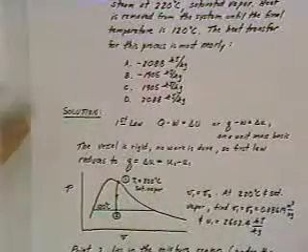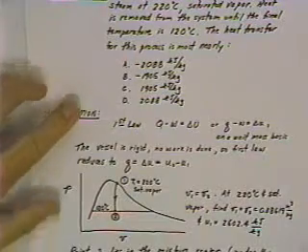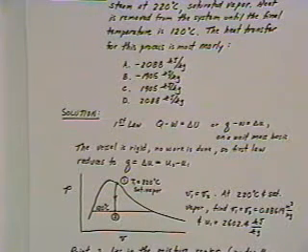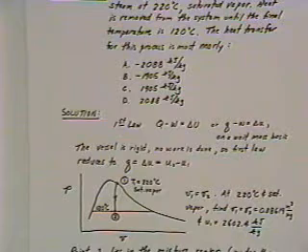If you're just looking at this problem, you can immediately eliminate answers C and D, the 1905 and the 2088, simply because both of these answers are positive. So you know your answer is either going to be A or B to start with, and you've eliminated two of the four answers right off the top because the heat transfer has to be negative for this process.